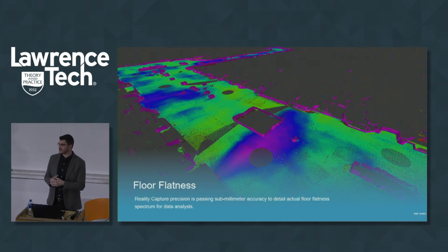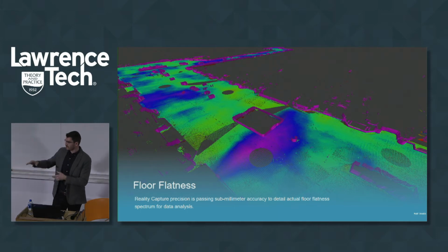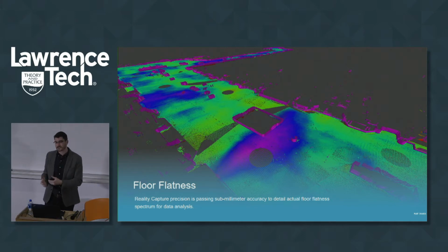With how detailed and dense this data can get, we're seeing the deviations in the floors and where they're going to start having issues, or potential predictions for where cracks will develop. Even when we represent where a floor meets a wall or where a wall meets a ceiling, we're assuming that that's a 90-degree angle. We're assuming that from this intersection to this intersection, that is a straight line. And we know that when we can scan these after they're built, they're not actually represented that way.